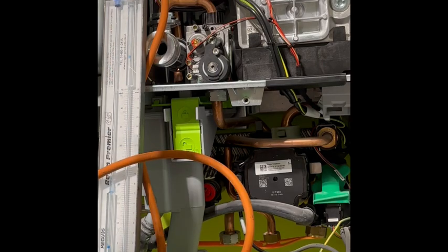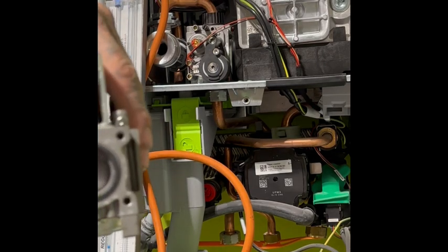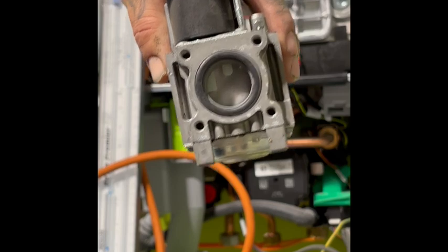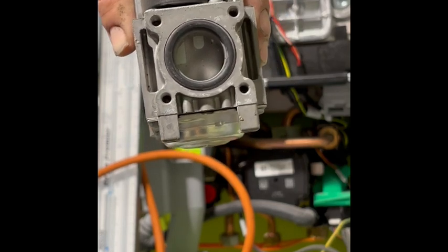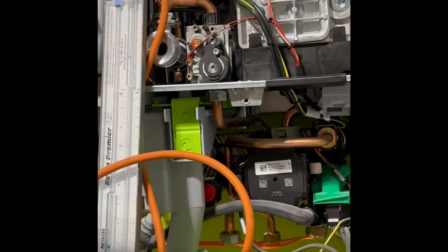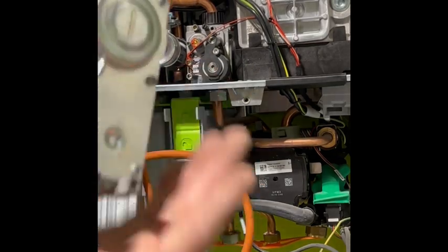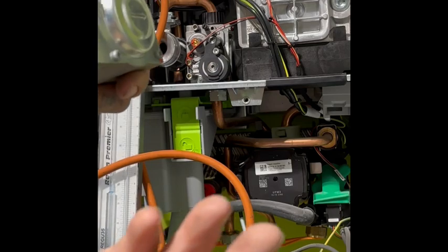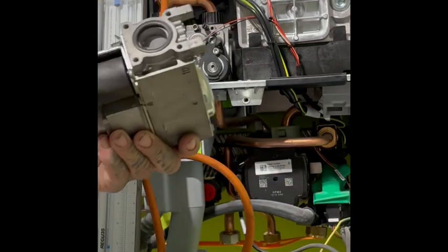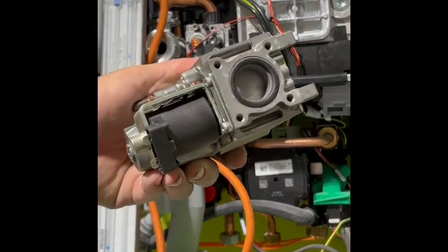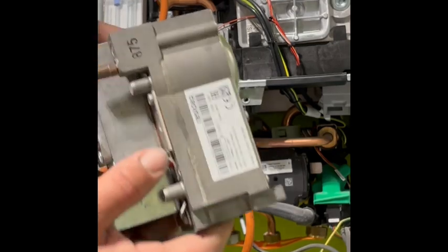Another thing to look at on this gas valve, if you can see that there's like a gauze inside that gas valve there. What can happen, which I've had a few times, is you get little bits of debris and shale in the gas valve. Just knocked a few tiny little bits out there. You get bits of shale in the gas valve, and that can block the inlet gas going in.